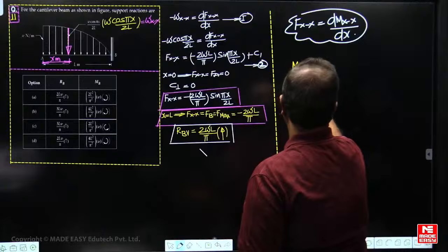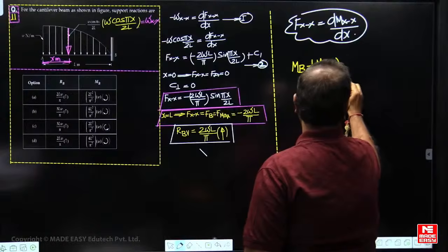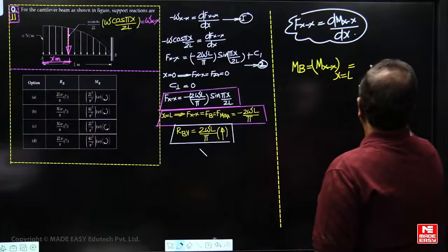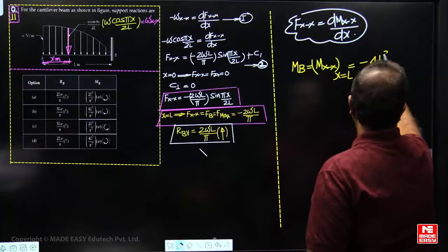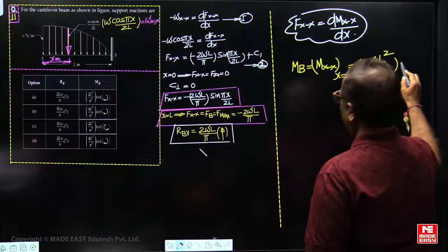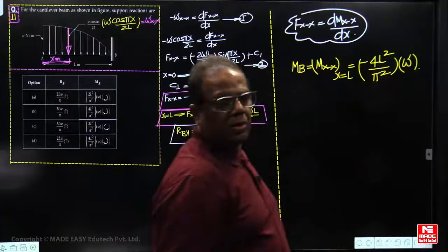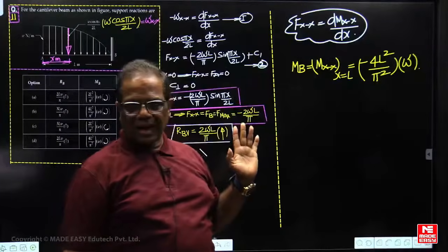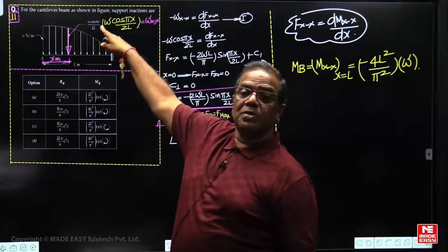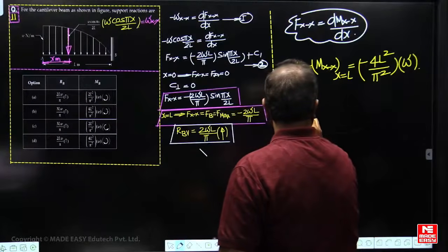So directly I am giving the answer for this. Bending moment at B, x is equal to L. So this value you are getting minus 4L square by... I am not giving the procedure directly, complete the numerical calculation. You are getting a negative. The bending moment is negative means what? Hogging. Hogging means it is going to be clockwise direction. So what should be the moment reaction? Moment reaction will be...